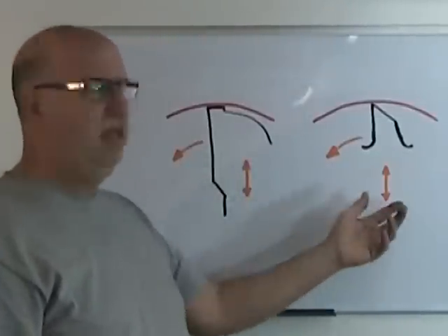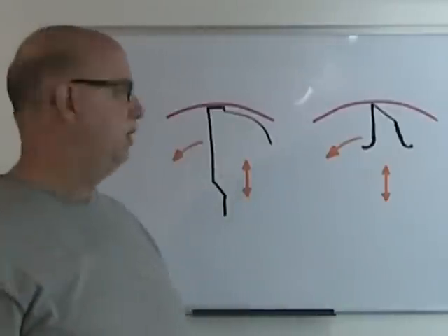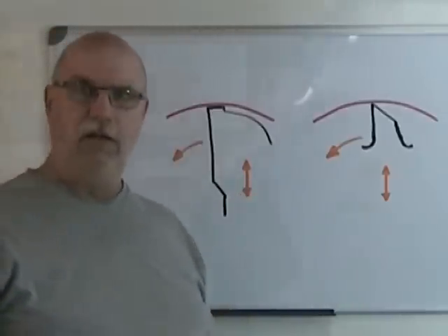We do not use a reamer at all in the same fashion that we would use a drill. So how does using a reamer and using a drill bit differ? Well, here I have a 7/16 straight flute reamer. And here I have a 7/16 drill bit. Feed, speed, and technique. That's how it differs. So let's take a look at feeds.